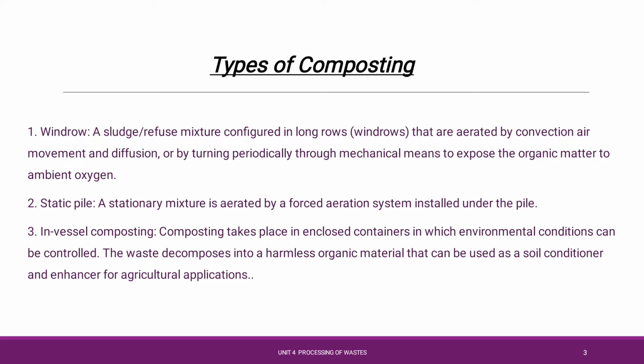Most municipal solid waste windrows are 1.5 to 3 meters high and are usually located on impermeable surfaces. The process efficiency depends upon the weather condition, and the process can be controlled through proper management by turning the waste periodically in order to expose the organic matter to the complete oxygen supply to get decomposed.